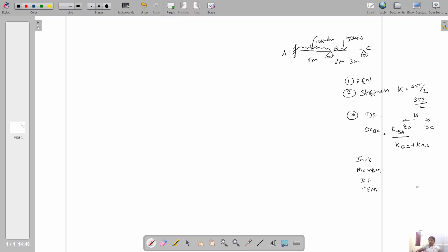So next, you find the unbalanced moment at a particular joint B, A and C, and also check whether the joint A is fixed and whether the joint A is simply supported. If A is fixed, that is the meaning of having the fixed end moment value at this joint. But when the joint is simply supported, we have to balance, or we have to make the fixed end moment 0 at the simply supported condition first and then proceed further.